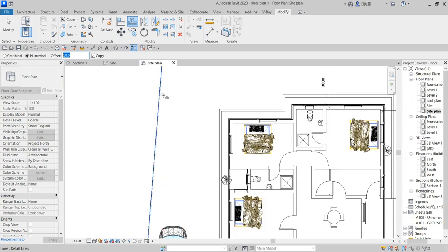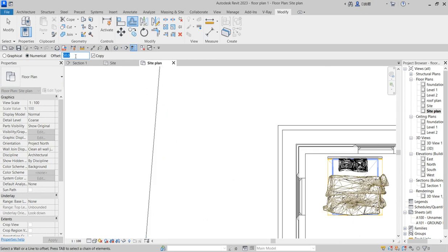This is the midpoint reference. So what you create is the level of the wall. At the middle you say 112.5. So this one will be the average of a 225 block wall. That is a 90 size wall, block wall.